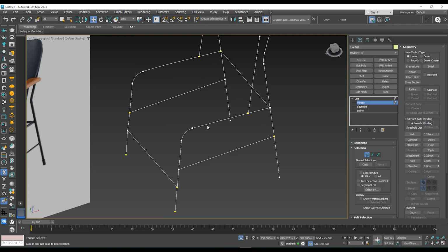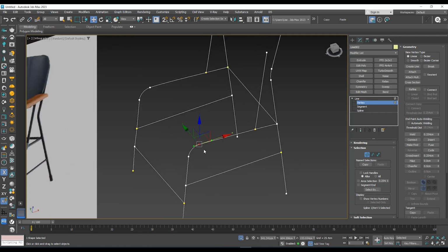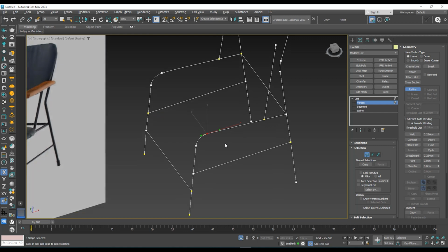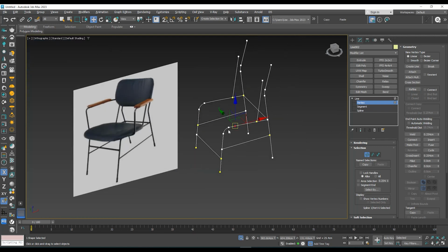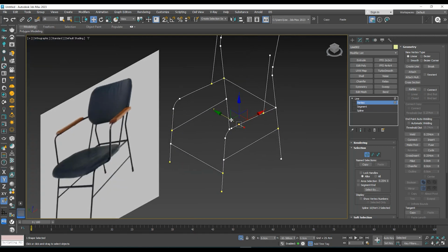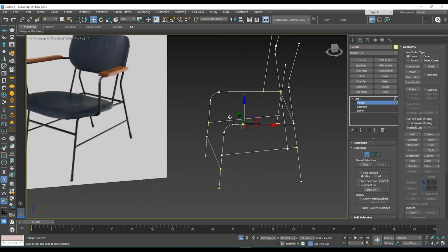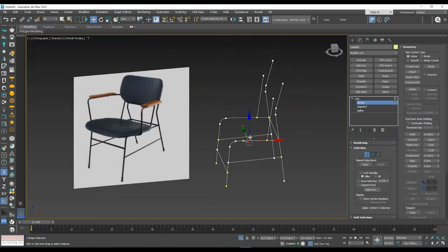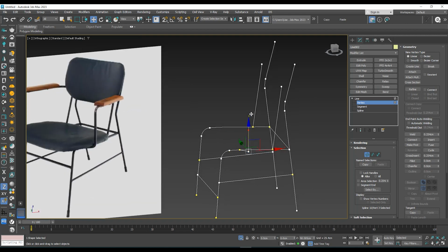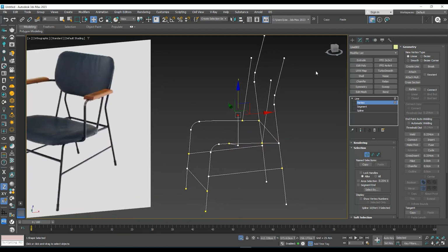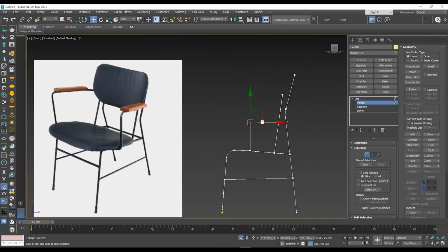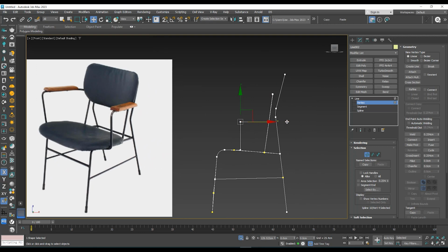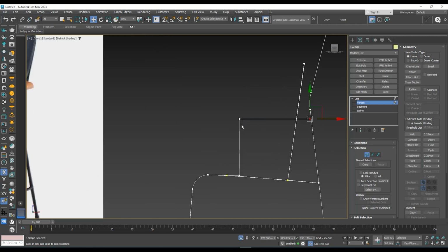You can make it from here, select one vertex, then another, refine over here, maybe here, then make it corner, then create like this, then again shift and then create. Go to the side view. Then now you can create it, your hand part.